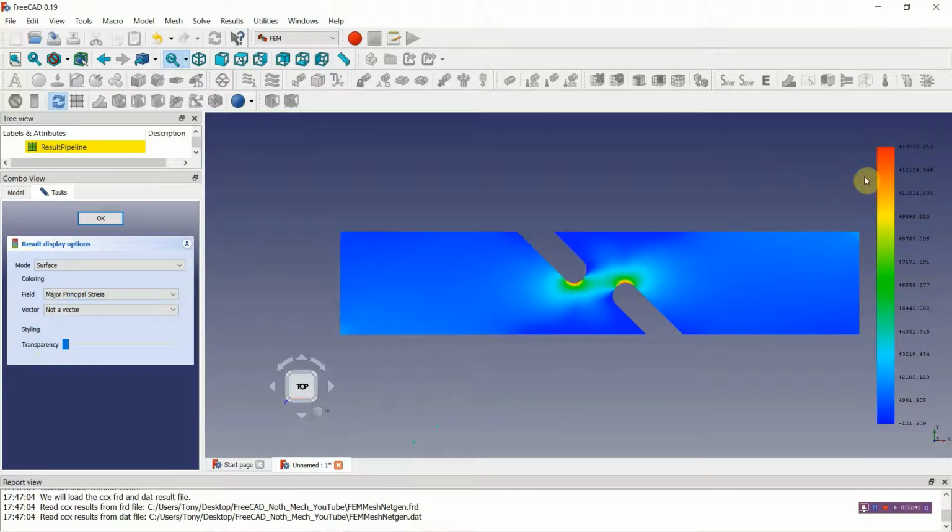So we have a maximum stress for this 1 millimeter displacement, which is extremely high. It's 13. We're in the units of gigapascals here. 13,000 megapascals, 13 gigapascals. So this is extremely high. I'm going to do an elasto-plastic analysis next, and I know that this is way over the yield stress of the material. We would not get a solution. I will have to reduce the applied loading from 1 millimeter here to about 0.1 millimeter to do this sensibly.